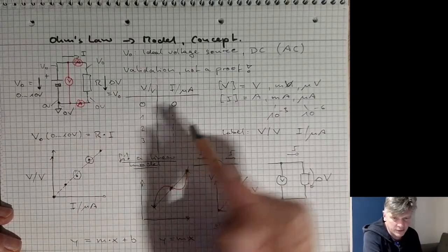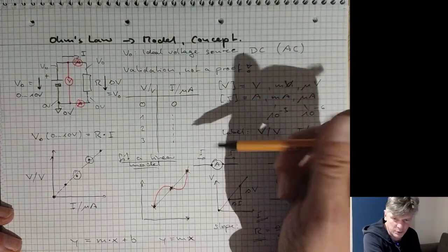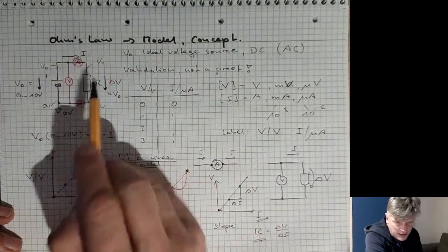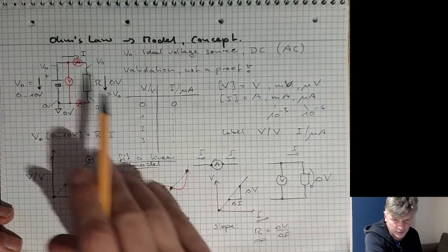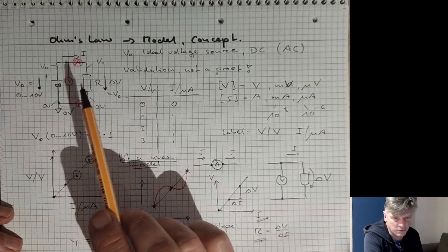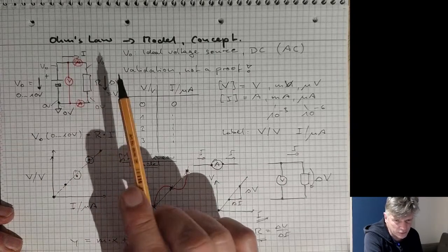And then you can check whether the power at some point exceeds the rated power for the resistor. And if you exceed this a lot, you are going to modify the resistor first, right?